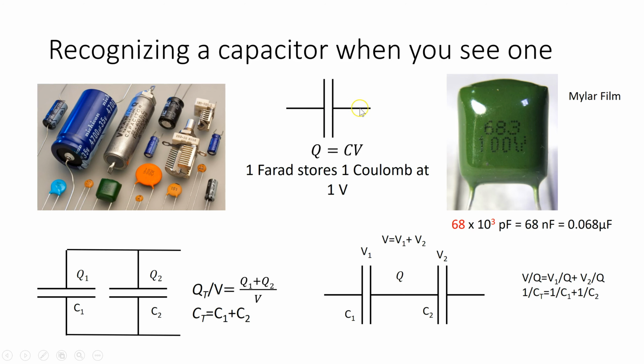When a voltage is applied across these plates, an electric field is set up between them, and in consequence these metal surfaces then have a surface charge related to the intensity of the electric field between the plates. If you then change the voltage across the capacitor, the surface charge will increase or decrease depending on whether you increase or decrease the voltage, with the result that charge will flow into or out of these leads, not across the capacitor but into or out of these leads. This time-dependent polarization charge is the AC current that passes through a capacitor.